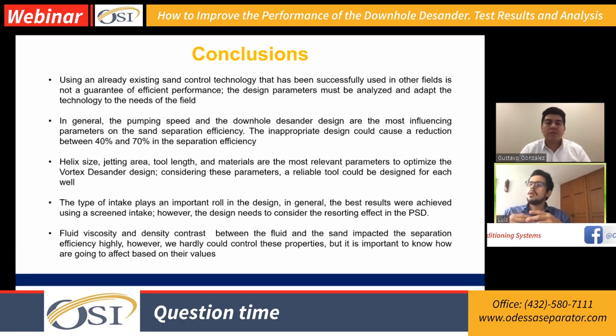What I mean is, not all the technologies are applicable for all the wells or for all the fields. You need to do a criteria analysis, and you need to choose the right tool. For example, if you are producing heavy oil and you are not reducing your viscosity, you are just producing a high viscosity fluid. This kind of technology will not really help you with sand control, and you may need to look at a different method, like homogenization, and then try to produce the sand.